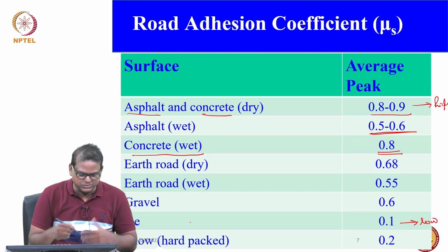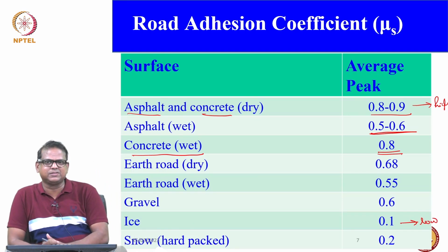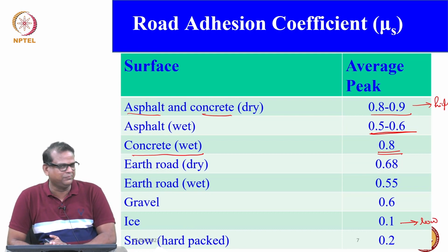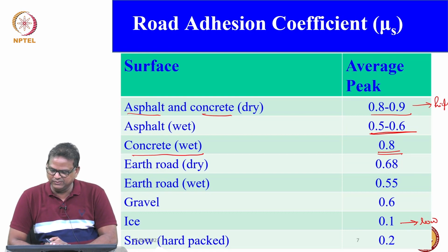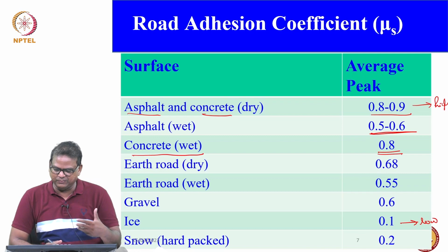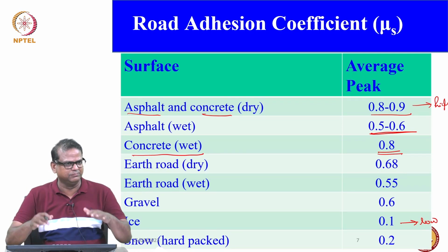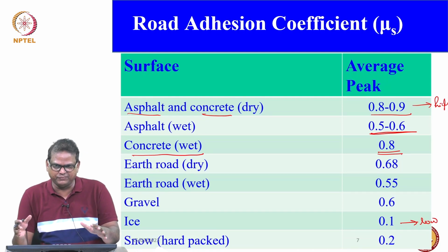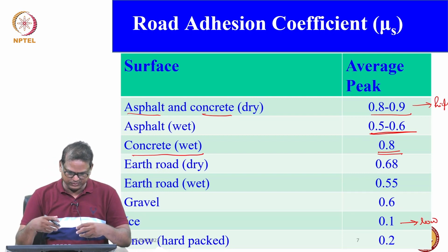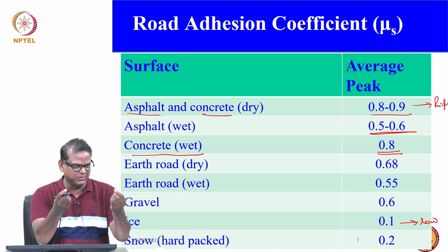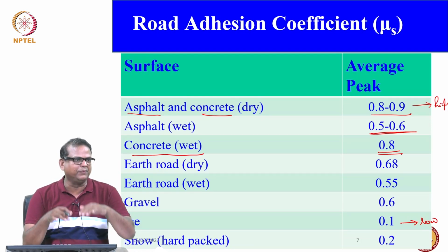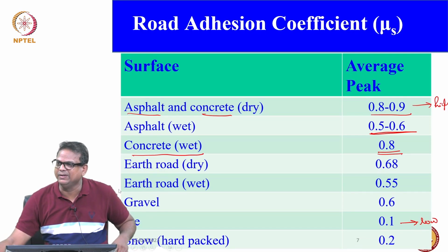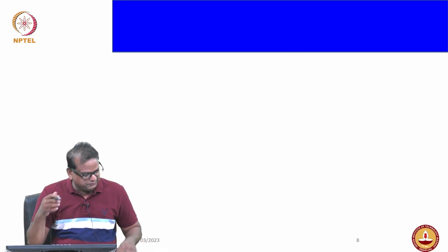Also when you have snowfall or icing, your coefficient of friction is drastically reduced. There, controlling your brake is very tough and difficult. In fact, when snow is falling, because snow is very loose, they make it packed to improve the coefficient of friction. On top of that, they pour gritty granules, which improves the friction and avoids skidding.